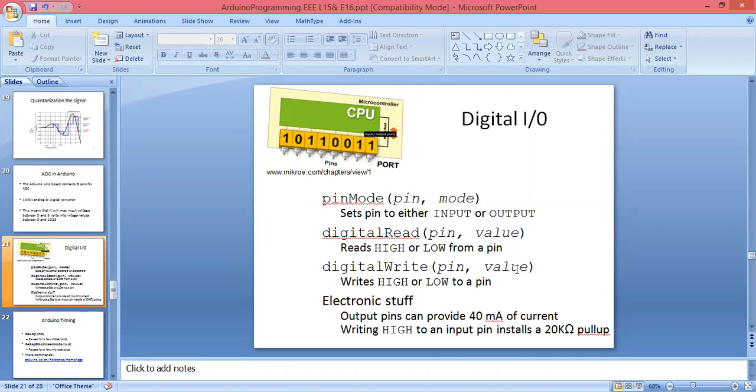That will be 5 volts. We know whenever we are using an LED, if we are not taking the inbuilt LED, which we get at the pin number D13, and we are taking an LED in our project externally, then the output pin can provide 40 milliampere of current, but the LED is capable of handling only 20 milliampere.